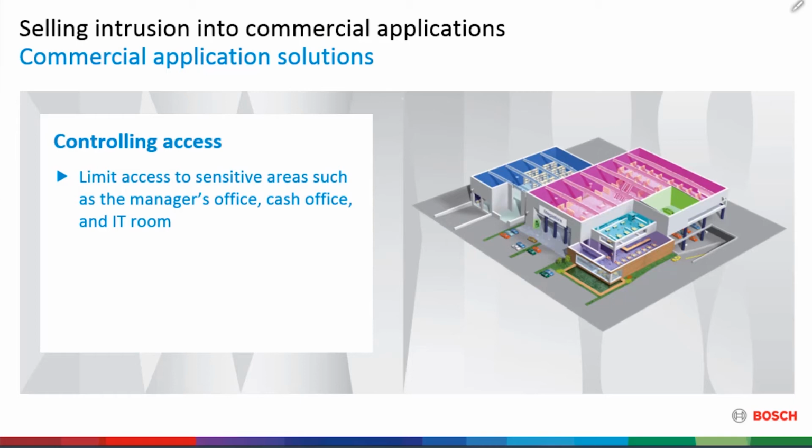We can program a Bosch panel so that each keypad can be told which areas it can disarm. So we can program it in that way so that you can either disarm the whole system, disarm just the place you're standing in, or any place in between. It's ultimate flexibility for your customers.